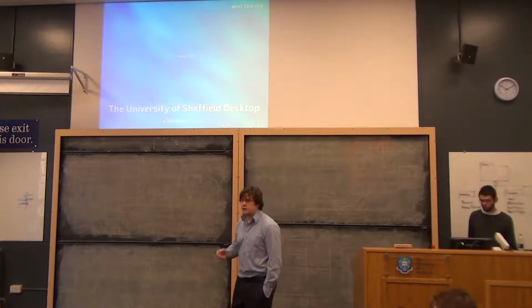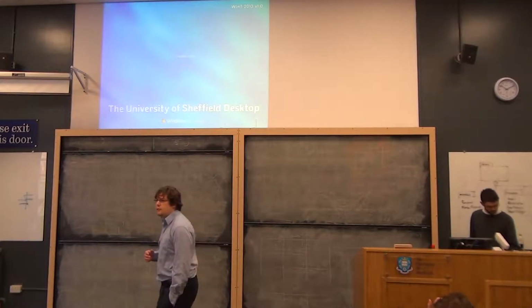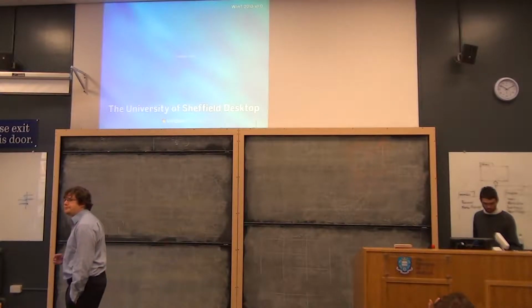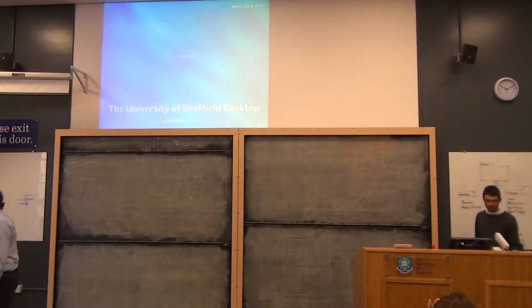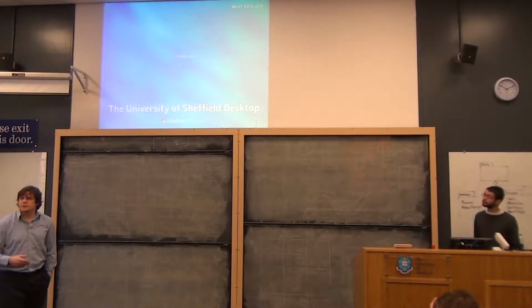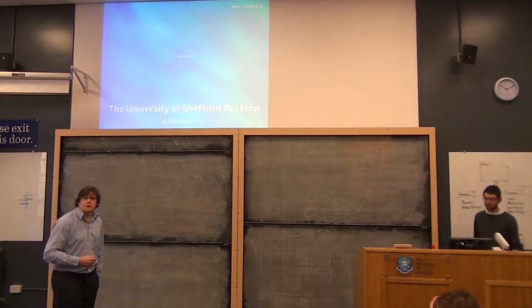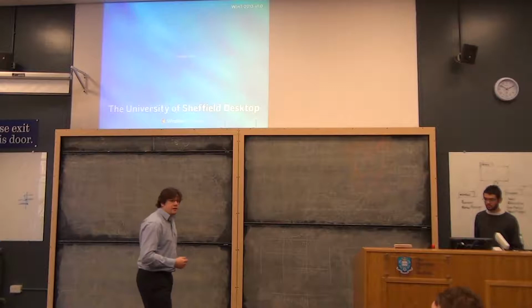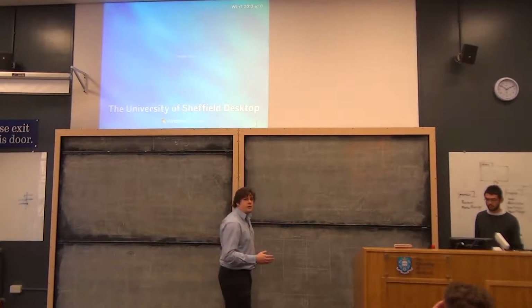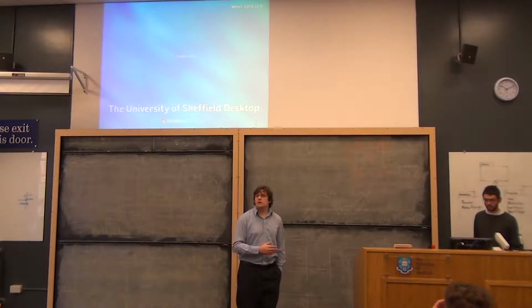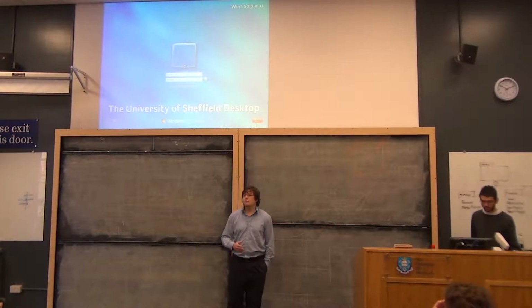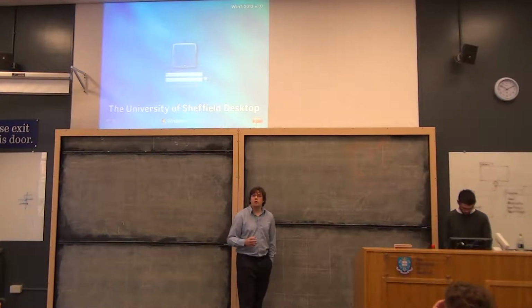A while ago I had a slide which showed the full range of permissible voltages in the UK system, and it's something like 220 something up to about 250 something. Anyway, stabilization is making your output indifferent to whatever the supply line's up to. Regulation is making sure your output doesn't change based on what load you put on.